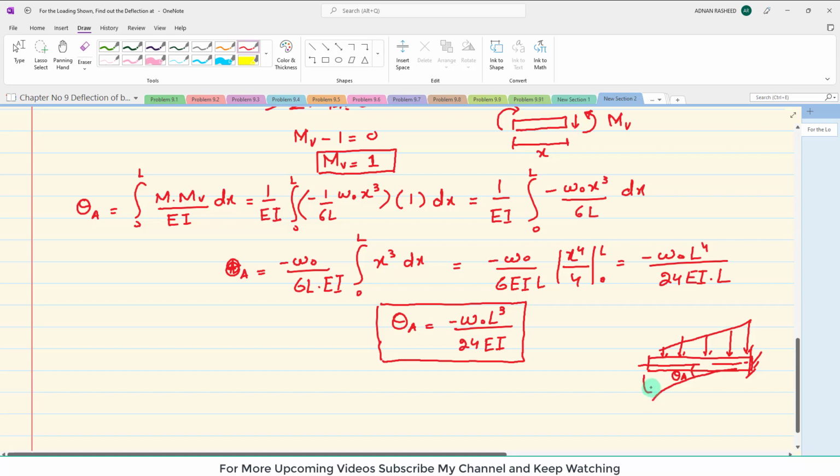You can see this is counterclockwise. Again here we have a negative sign, which means clockwise direction. So our assumption in choosing the direction of the moment was wrong. So we can say that this theta A will be equal to W naught L cube over 24 EI, and this will be in the counterclockwise direction.